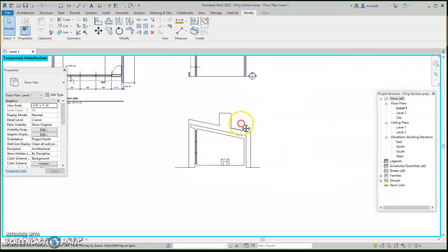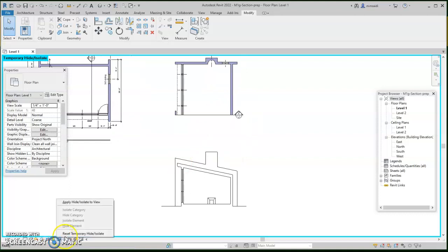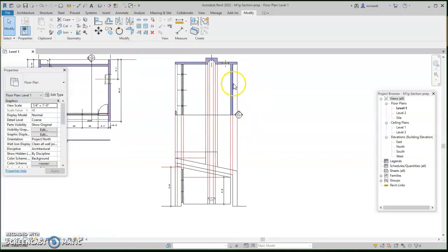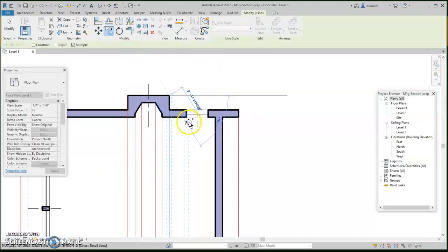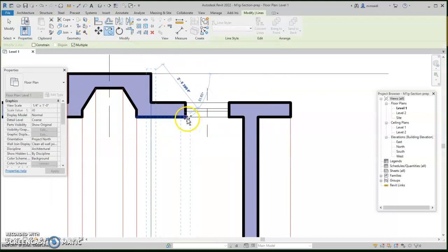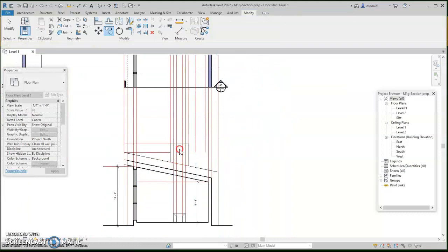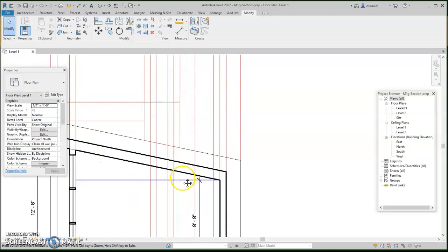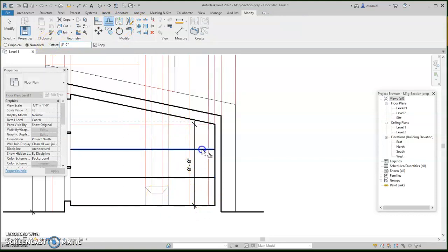Now I would like to place the window. So I'm going to turn on my construction lines and begin another construction set of lines. So I'm going to copy this one from that junction, place it at this corner, this corner. That's my window. I'm going to extend those 2 lines to the floor. My window is happening 3 feet above the floor. I'm going to set it up at 3 feet above the floor. And then another 3 feet is over there.